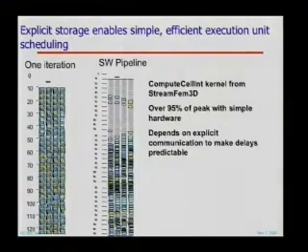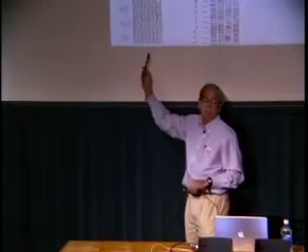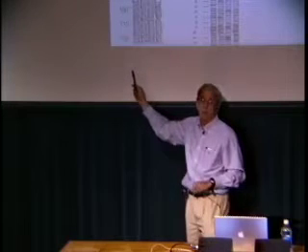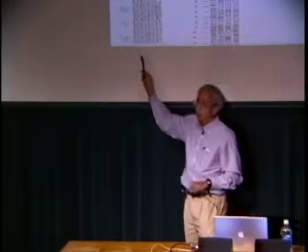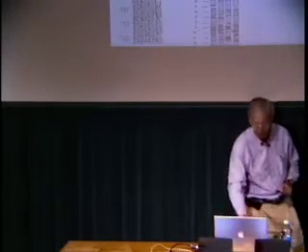So the ability to statically compile the code occurs because we've factored things out. The technology that's going on under here is something called communication scheduling. It takes into account the fact that these 4 multiply-add units are actually fed by 12 separate register files, one on every input of every function unit, and the communications have to be scheduled from the outputs of function units over switches into the appropriate register files for where the next operation takes place. It's actually an interesting compiler technology.